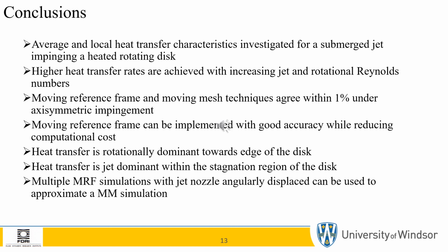Finally, multiple moving reference frame simulations with the jet nozzle angularly displaced can be used to approximate a moving mesh simulation. However, the accuracy of the moving reference frame for axisymmetric cases should still be addressed.